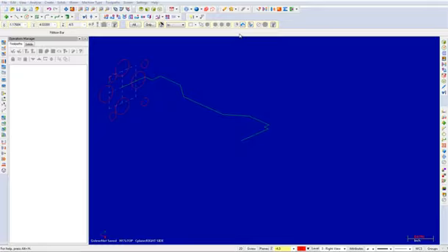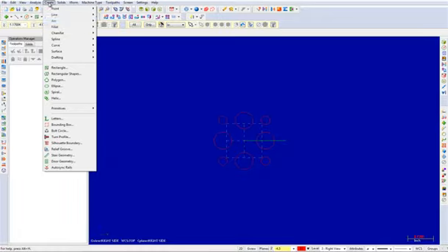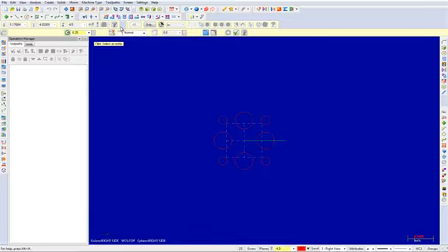Now we will fillet the 1/4" radius circles. The first thing we must do is select the right view from the toolbars. Then choose the Create Fillet Entities command. Input a radius of 0.25, set the style to normal, and ensure no trim is enabled.